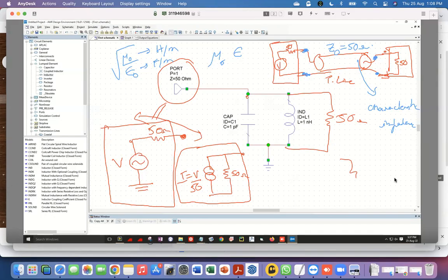But from this point to this point, the transmission line has some voltage and current which is varying with space and time, of course, because these are all oscillatory signals. At the boundary conditions, at the ends, you can again define those numbers, and that's what I mean by ensuring this ratio at all of those points is equal to this particular value, 50 ohms.